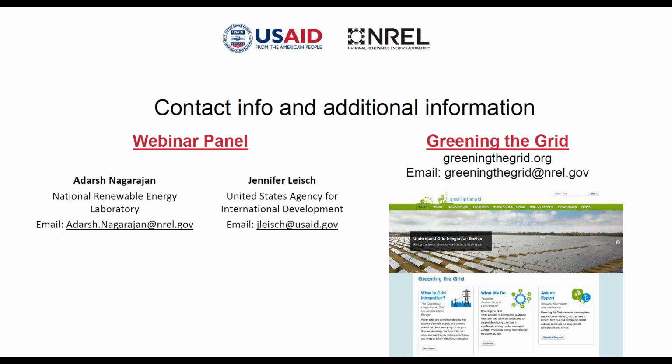And that's the reason why 1547 came up with 3 categories to identify how to behave or how not to behave. As I said, category 3 is what Hawaii and California have chosen, for when to island. The idea here is to be able to identify what the device should be doing when there is a fault.